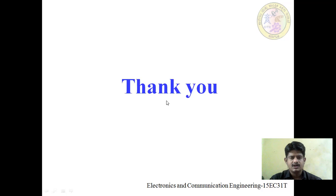So we are coming to the end of this session. What are the topics we have discussed? Let's revise. We have discussed the parameters of a half wave rectifier: IRMS value, IDC value, ripple factor, efficiency, PIV, output frequency. Then we derived the ripple factor and efficiency of a half wave rectifier. After that, we discussed the parameters of a full wave rectifier: IRMS value, IDC value, ripple factor, efficiency, PIV, and output frequency.